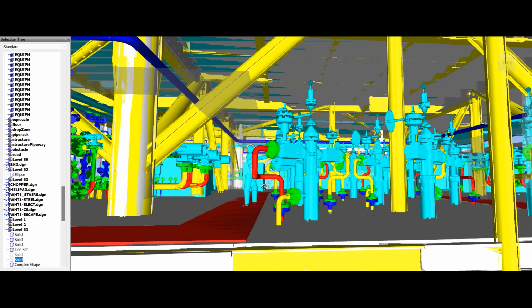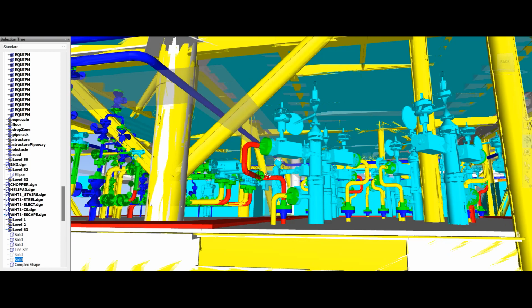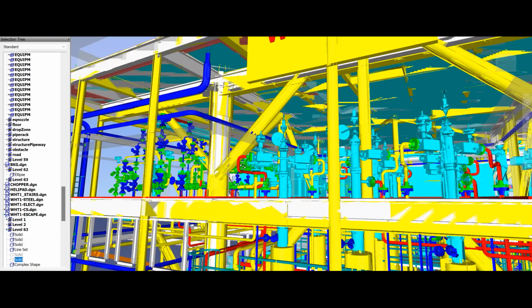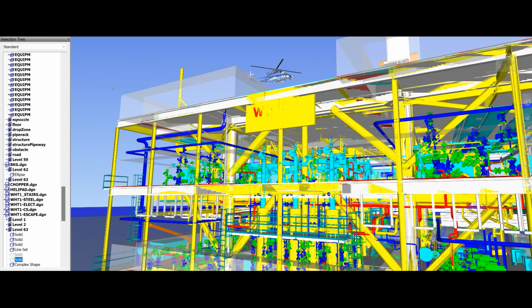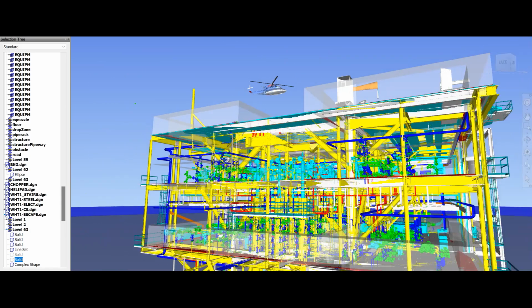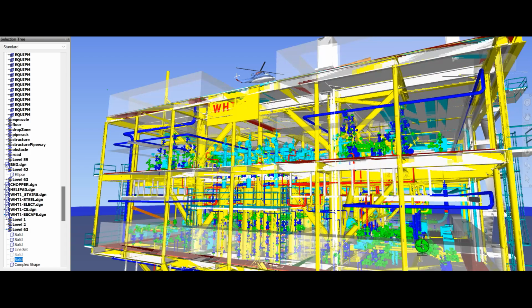And then there are the temperature indicator, thermo valve, then choke valve, and after the choke valve the line is split into two. One is going to the production header, the other one is going to the test header, and the test header is going to the MPFM to measure the quantity of oil, gas, and water. And again after the MPFM, all these three things are combined together and connected with the production header.